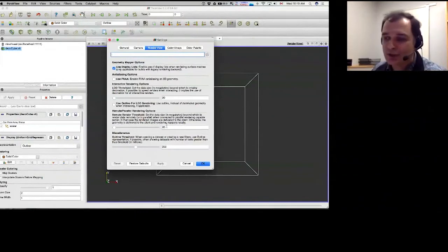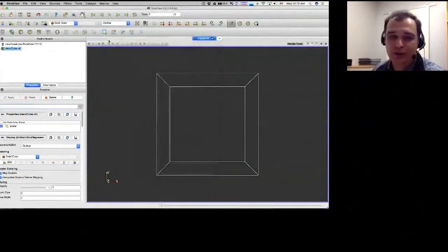So if I set this to 0, then all rendering will be happening on the remote machine. It'll be very slow. That's why you want to set this to some reasonable, not 0 number. And then small scale rendering will be happening in, sorry, in OpenGL, not WebGL, in OpenGL on my laptop using the graphics card on my laptop.